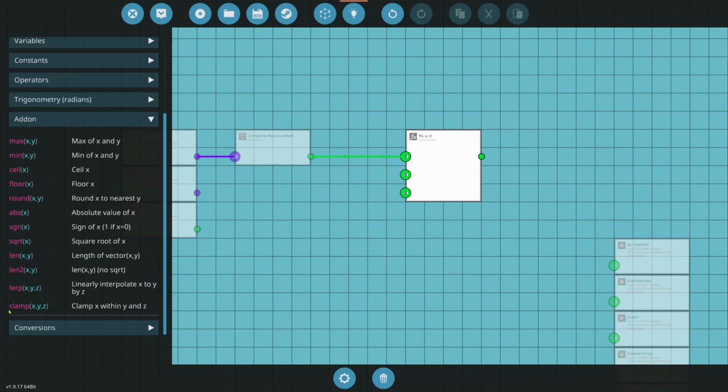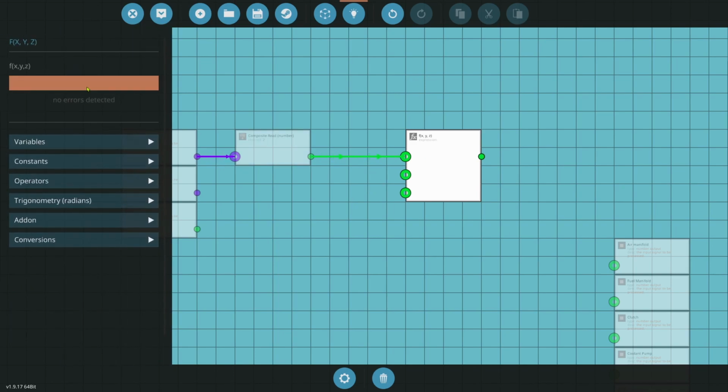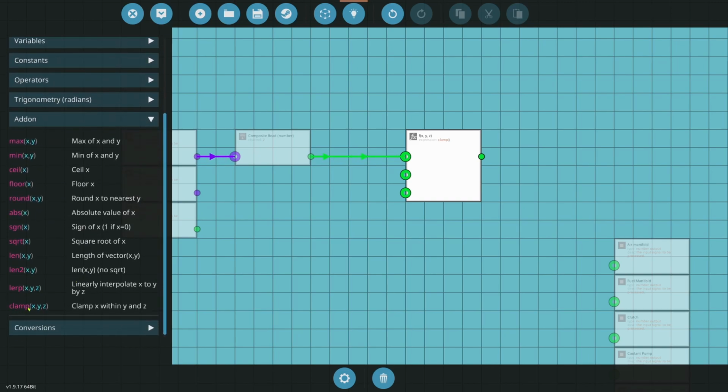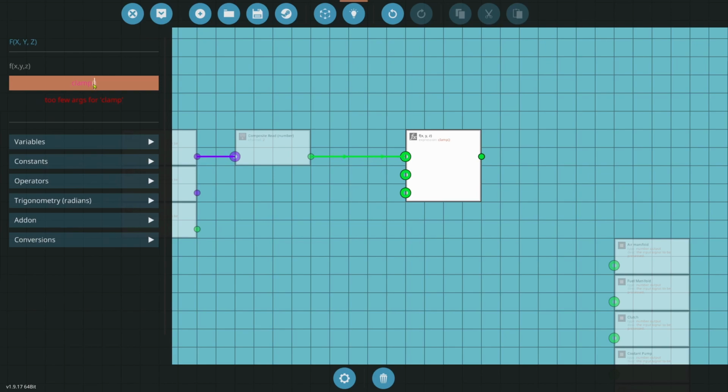And so what we're going to do here is we're going to use a clamp, and we're going to put that in. So let's go ahead and we'll type clamp. And then we're going to put parentheses. So if you ever have an issue with this where you forget, just come back and look. It should look like this. Clamp, parentheses, X, comma, Y, comma, Z, parentheses. That's what it should look like. All right, so here we have our clamp. And now inside of here, we're going to go X times Z, comma, Y, comma, Z.